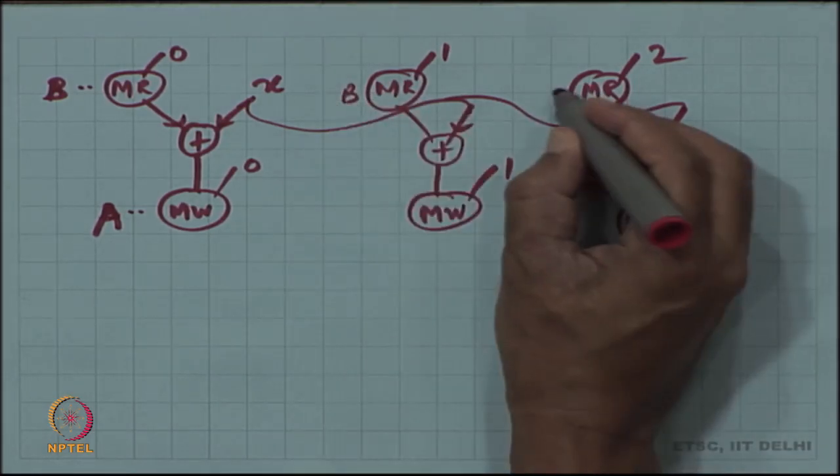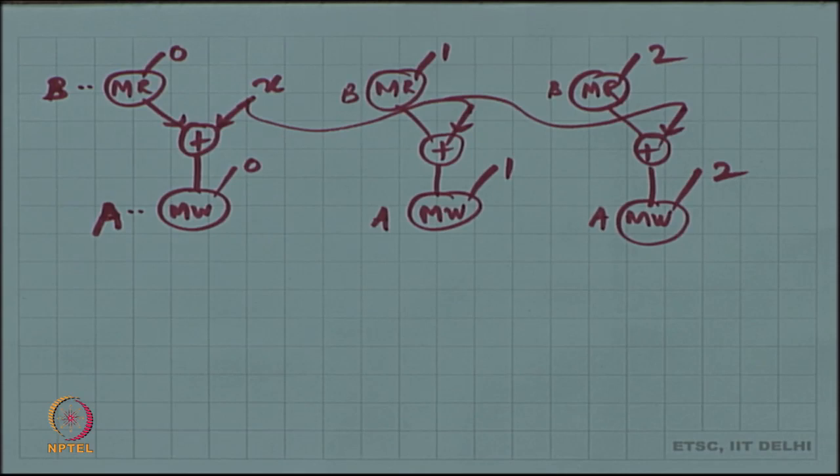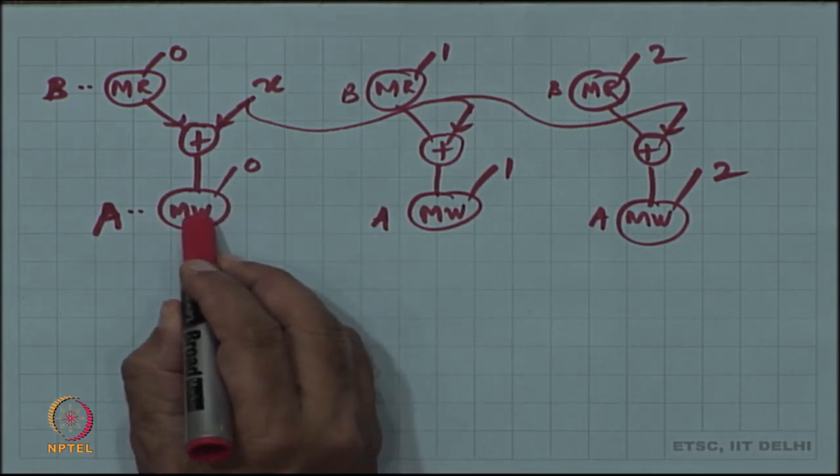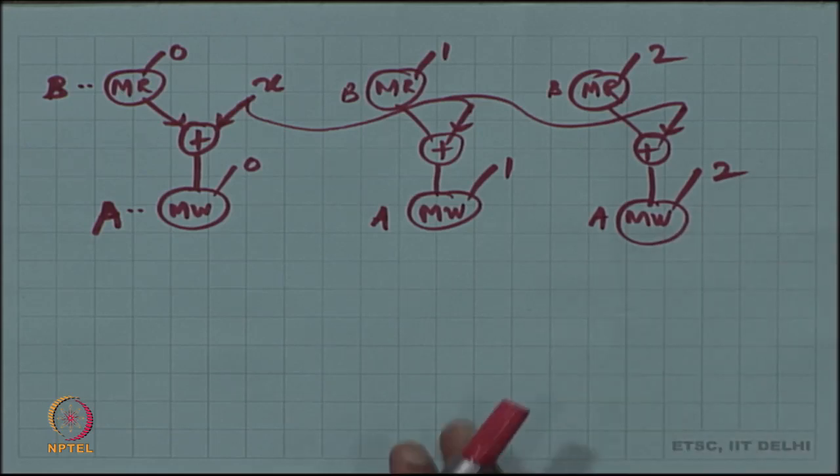For now, I will just label them. This is just the DFG. DFG is still correct irrespective of how you are going to synthesize it. So, what optimization opportunities are there? Let us take a look, but here is a memory write into A, memory write into A, memory write into A. Addresses are different, but that is my DFG. But that is not the end of it, as you identified. Now, if I schedule this, how many cycles will this take?